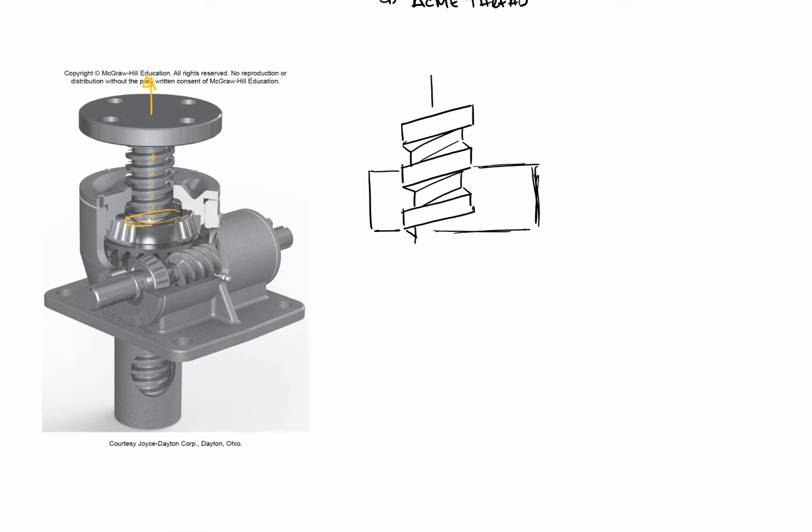And so basically what you have is a force going up or down. So like, I don't know, the weight of this power driven jack, and what you would see is that there are some reaction forces from the nut that are counteracting that force going down. So this would be F over 2 and F over 2, right? Now again, just to analyze the forces, we're going to use one complete revolution of a thread.